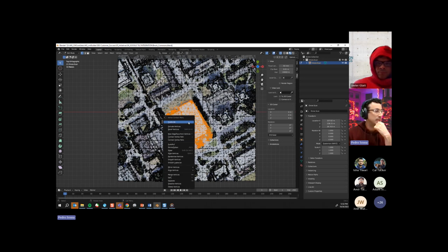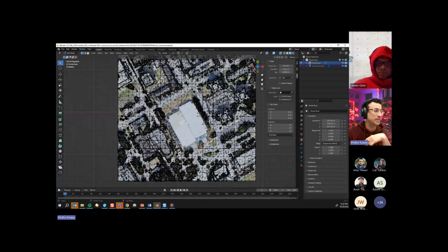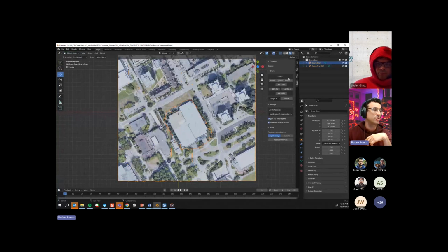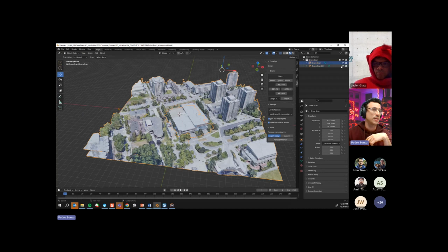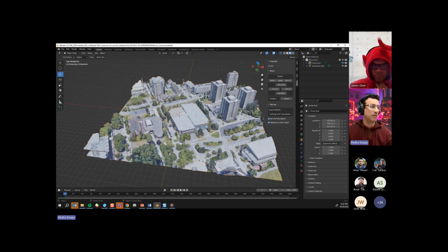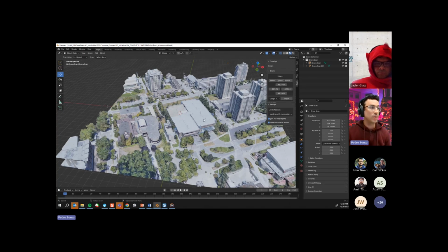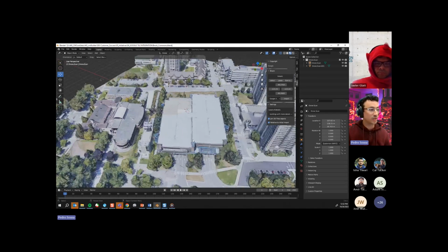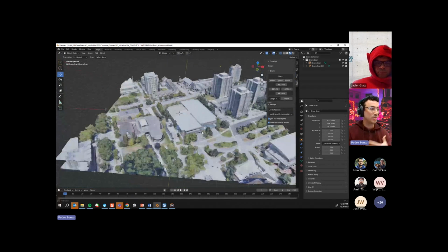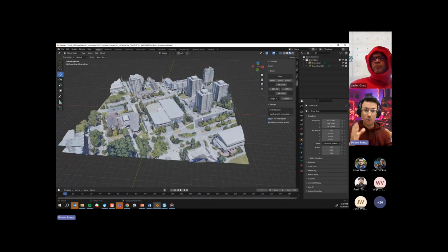So you can do something like this in Blender where you can separate the selection of elements that you have. And now, you can see over here in my tree structure that I have two different elements, right? So I just created an opening on my site to show the stage of that area of that model once you demolish that part. So this can increase the graphics and the visual impact of your simulation by a lot. And if you want to go even further, there are some tools in Blender and other software where you can slice this into smaller pieces so you can show the staging of your demolition as well. This is something that we usually suggest for customers that are working with more detailed demolition steps and so on and so forth.